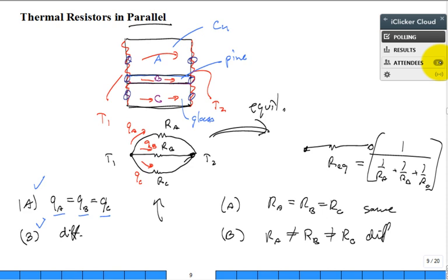Would the temperature on the other side be the same? That's the challenge of having them in parallel. Okay, that's what was confusing me, because I thought the temperatures would be the same on both sides. Whenever you have a parallel, it's assumed that these have to be the same. Now you're asking, experimentally, how am I going to do that? Well, you're probably going to put a slab over here that's a really good conductor to help it stay the same. Or maybe you're going to flow fluid aggressively at that uniform temperature across that surface to keep it the same. But yes, that's part of our assumption that those are the same. And if you were tripped up on that, I can see where that would lead you to try to make them different.